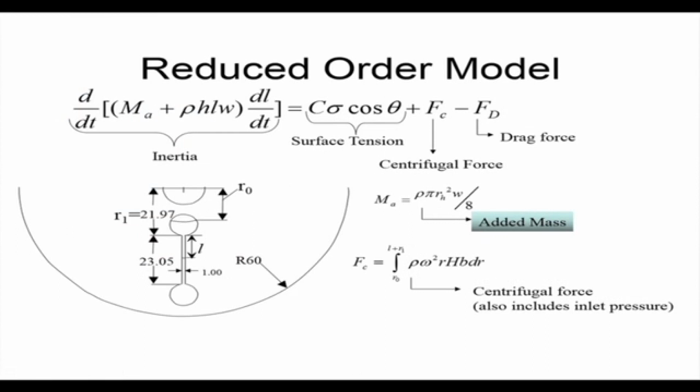So the reduced order model, again we are coming back to the capillary filling problem. You can see that we have done the capillary filling problem earlier with the left hand side the inertial effects, this L is like the S parameter that we had, that is the instantaneous displacement of the capillary front within the channel. Surface tension, drag force, we have added one force, that is the centrifugal force.